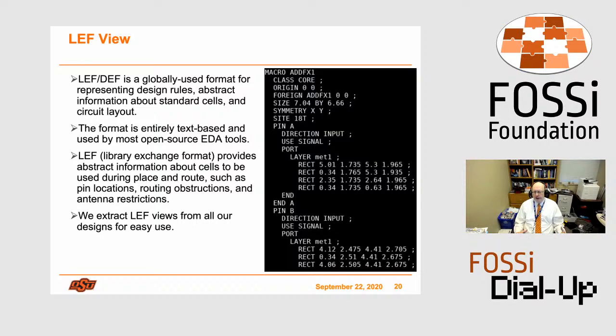And it provides really abstract information on the cells. You can see an example one here for a full adder. And we extract LEF views for all our designs so that they're easy to use and all provided.